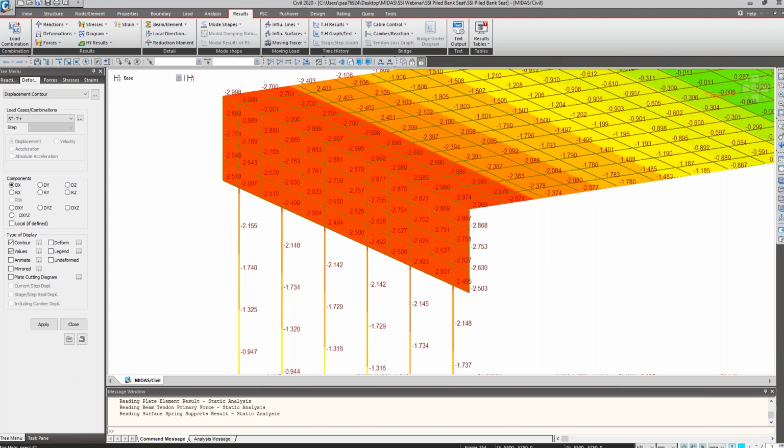Another question is, is it possible using Winkler spring multilinear for PY curves and TZ also. So TZ is, instead of using laterally loaded piles, that's for vertically loaded piles, which is commonly used on software for pile analysis. And yeah, that can be used. It's just you have to make sure that your nonlinear spring, instead of being aligned on horizontal direction, is aligned on vertical direction, and you define the TZ curve that you want to use. So that's completely possible. Yes.